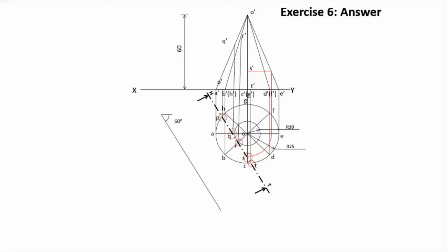Then the point corresponding to OS will be lying on OE at this point. That is the point where the circular arc and OE intersect. And from there we draw it to the O dash E dash, which means we find out the distance of that particular point in O dash E dash. Then drawing it towards the left, the same point is projected to the O dash C dash. So that is the concept. Likewise, you can find out S dash also.